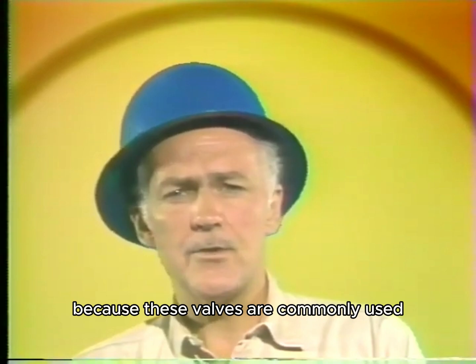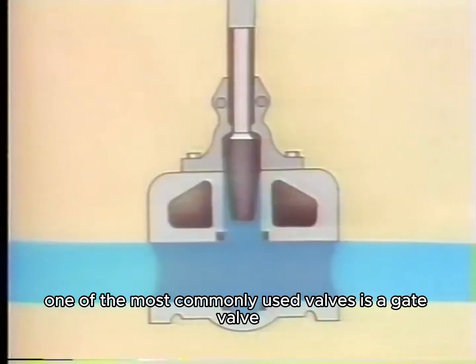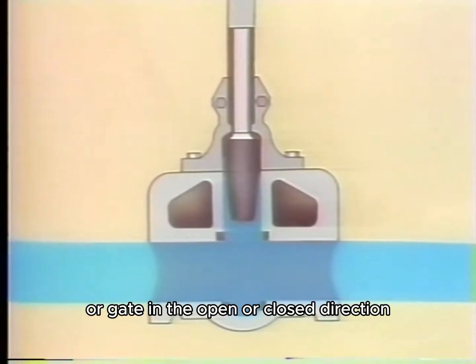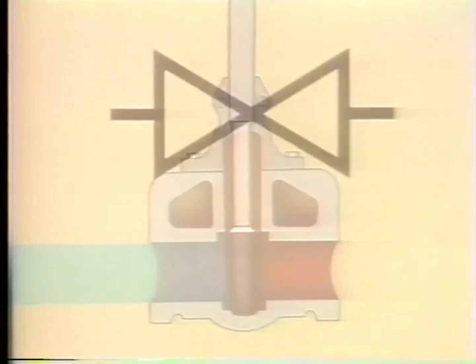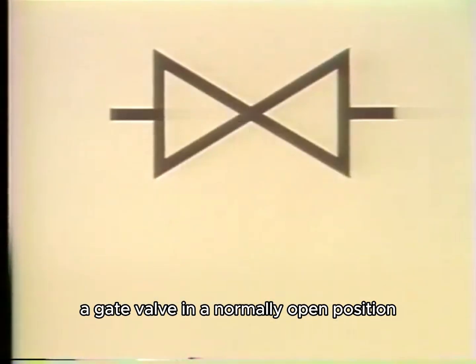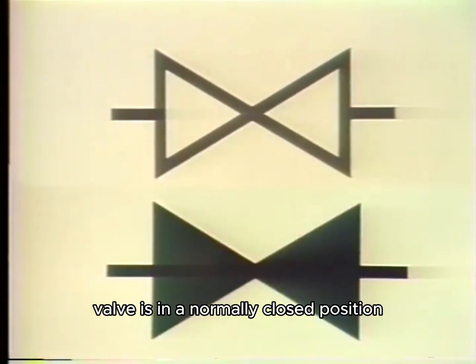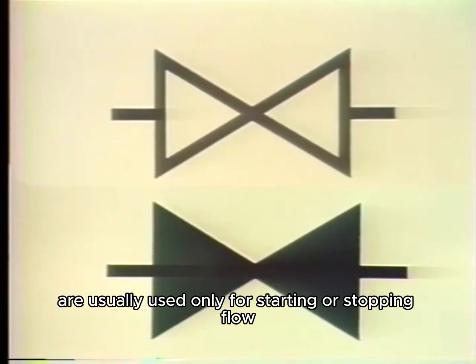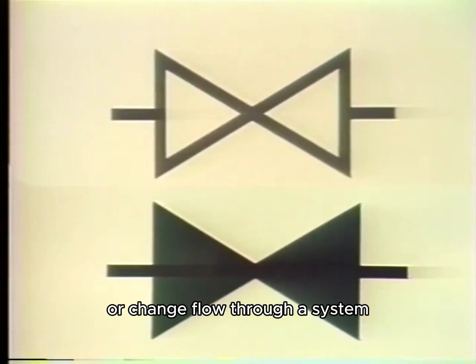Because these valves are commonly used, let's briefly look at two types of these valves. One of the most commonly used valves is a gate valve. A gate valve operates by moving a disc or gate in the open or closed direction to either start or stop flow through the valve. A gate valve in a normally open position is symbolized like this. The symbol is modified when the gate valve is in a normally closed position. Gate valves are usually used only for starting or stopping flow. They are not used to control or change flow through a system.